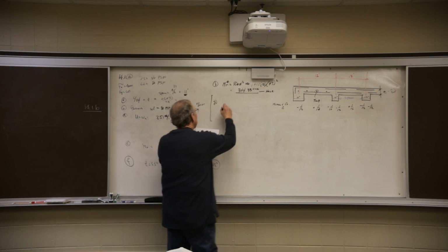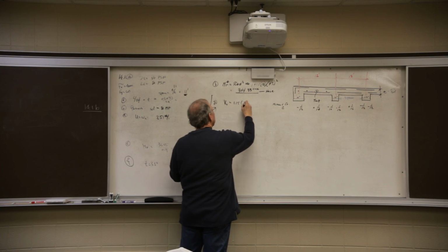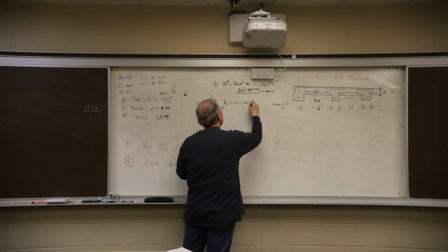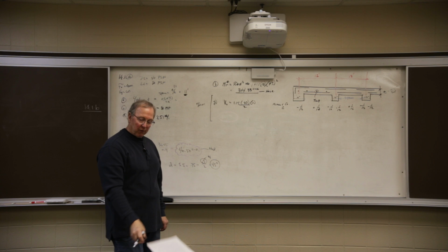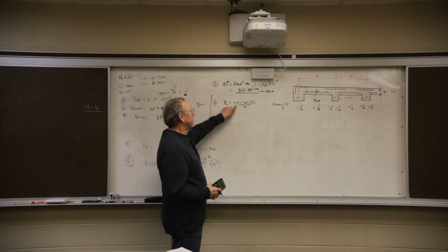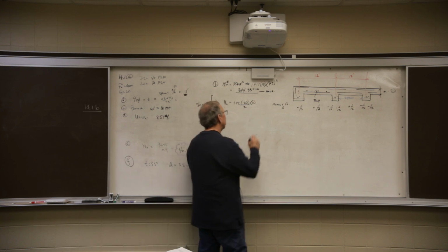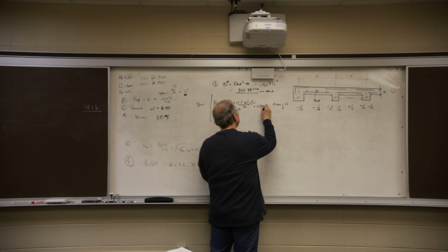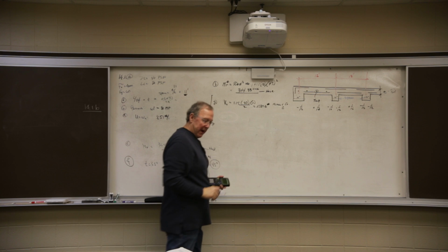Let's do VU. Safety factor, load, span. I don't know if you can see that, but I just did. Hopefully you can. That finds the reaction on the left-hand side multiplied by a safety factor. So 251 times 11 times 1.15 divided by 2. That's 1,587 pounds. Then move down to the next step.